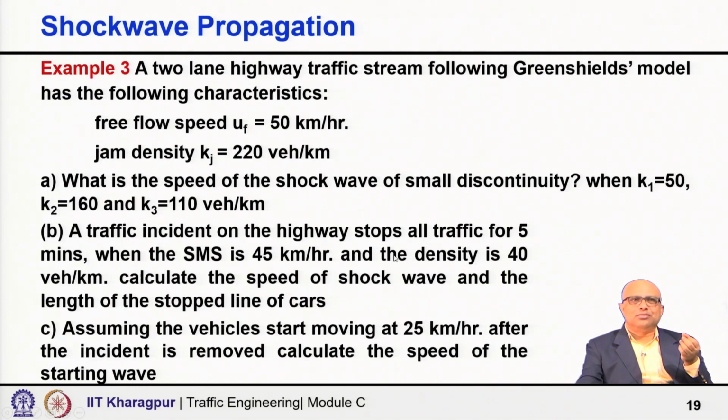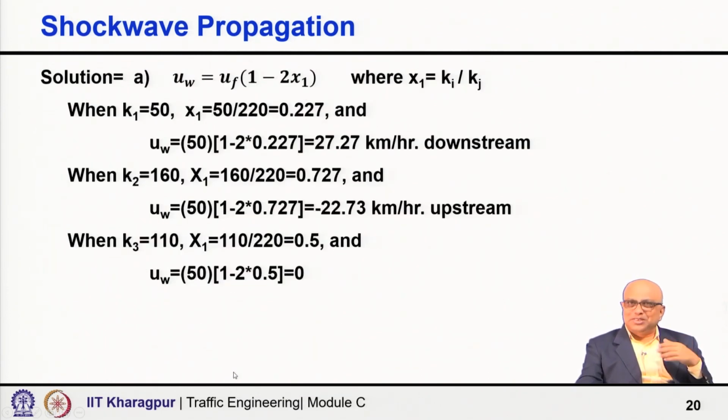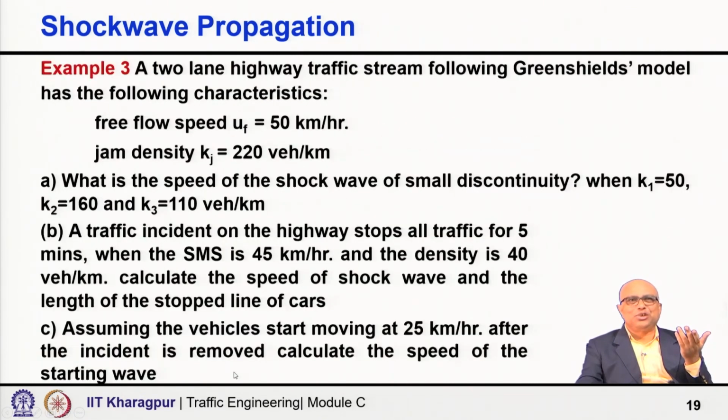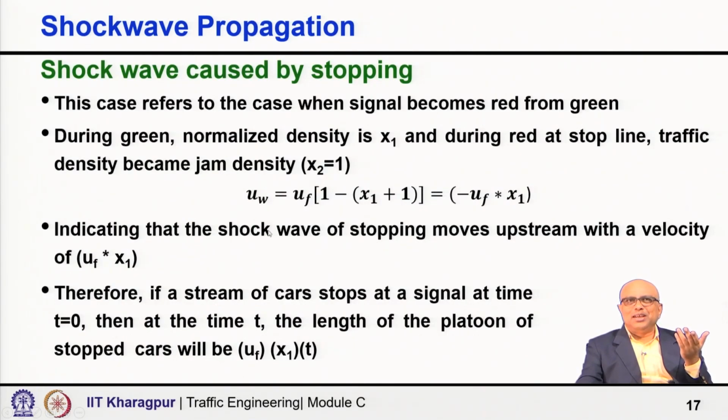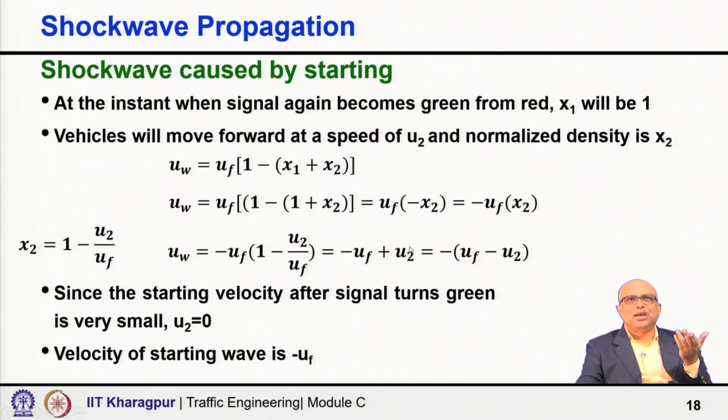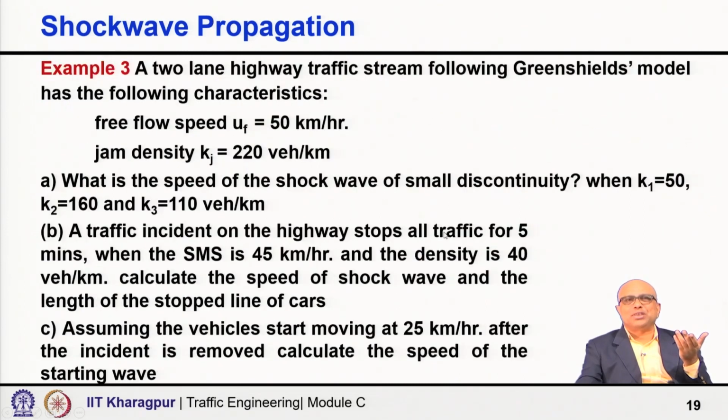Third, assume that the vehicles start moving at 25 kilometer per hour after the incident, that means after 5 minutes. Calculate the speed of the starting wave. This is the other case. I told you 3 cases here. One is shock wave caused by nearly equal densities. Then we discussed also the application of shock wave caused by stopping, and now finally shock wave caused by starting.